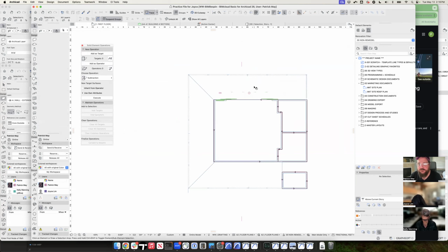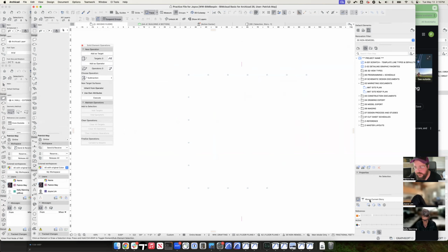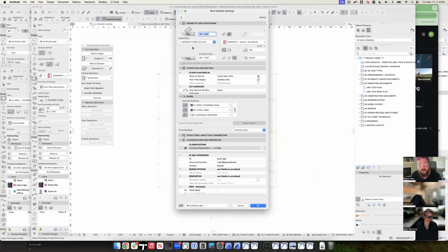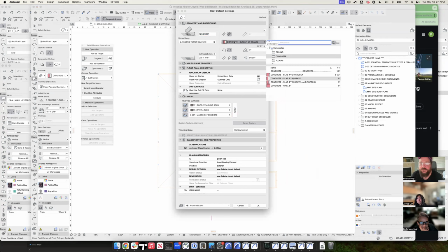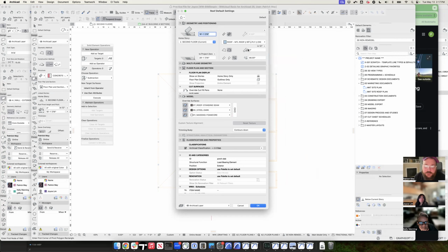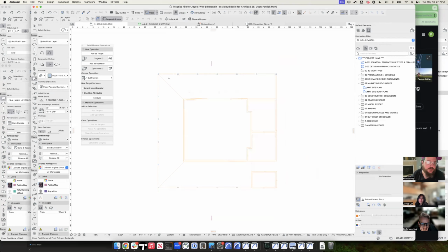So now I want to go to the roof and we'll say show below current story. And I want to demonstrate the other roof method here. So if we go to the roof tool and we say that this thing is going to be a multi-plane roof, and we'll say that it's a 3 and 12 slope. The roof is going to be, we'll say it's roof 2x6 metal roofing. Standing seam, that's all fine. We'll leave it at that.